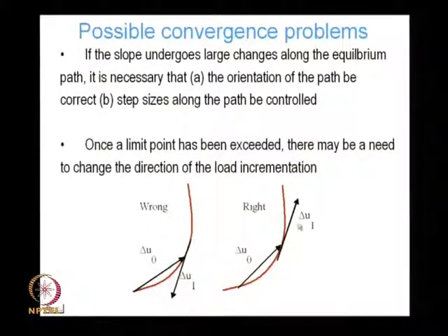So, the right solution is actually checking the orientation. The actual right orientation is this. If I take a displacement increment in this direction, I will be totally lost. Once a limit point has been exceeded, there may be a need to change the direction of the load incrementation.